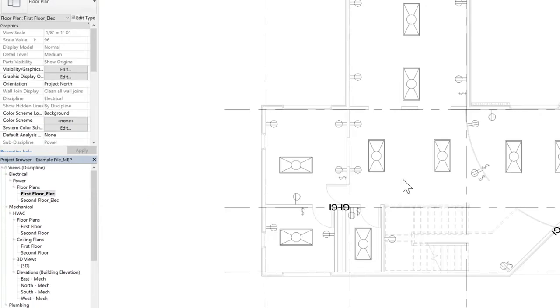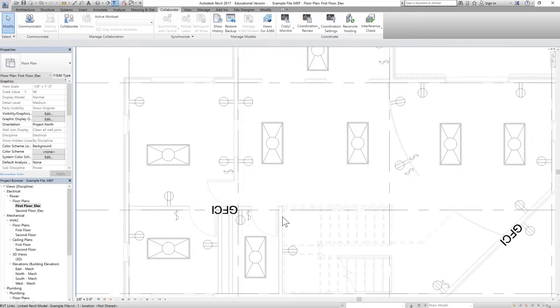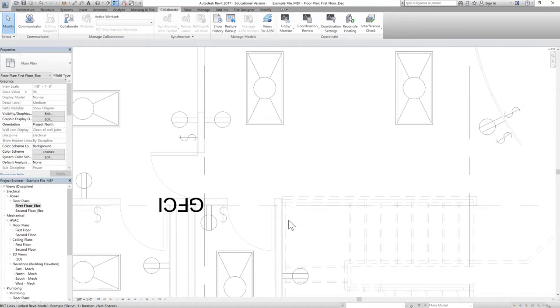So just like our HVAC, in which we created a system of duct, now we have to create a system of circuit. So we'll be creating two types of circuit. One is control circuit, one is a power circuit. In order to create a power circuit, we need a panel board. There are two panel boards, one on each floor. So let's say on first floor, there is a panel board below a staircase right here.